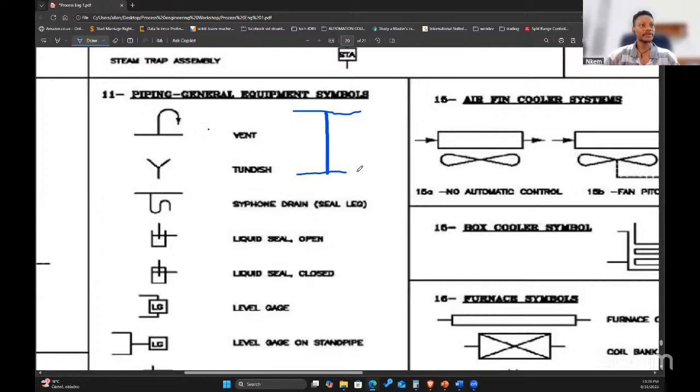This is 0, and this is 5. This is the design maximum. This is the design pressure for a line, a pipeline, for example, or a vessel. And then you have an operating window. Let's say the operating window is probably at 3 bar. It means you're operating this process between 0 bar and 3 bar.